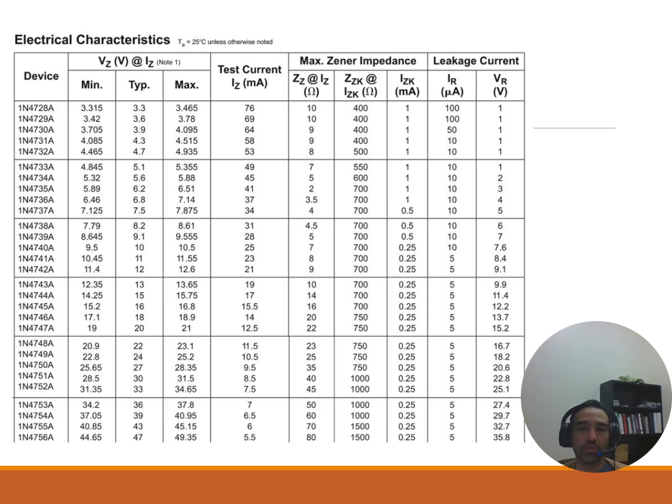So when the voltage is below the Zener breakdown voltage, it just means that you'll still get some leakage current. You can't say that nothing gets through, right? So you have to deal with that. And that can lead to things like inherent error in devices, things that you just have to work around in your design. It's going to exist there, and you have to deal with it, right? So your circuit has to be able to deal with it.